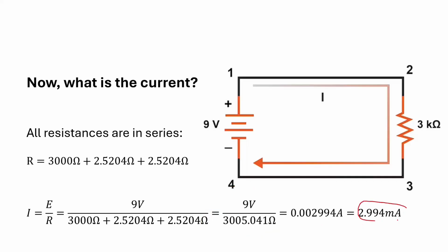And instead of 3 milliamps, we have 2.994 milliamps, which is a measurable amount. It's 4 significant digits instead of 3, but it is a measurable amount, and you may see that on your multimeter as a difference, right? And so there is a difference, and that is important.